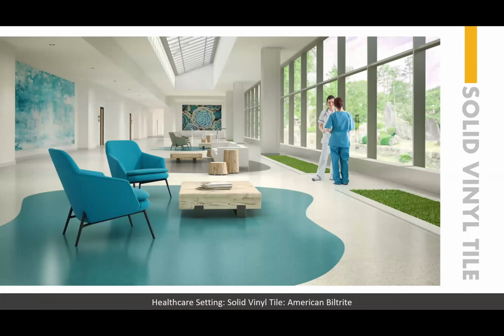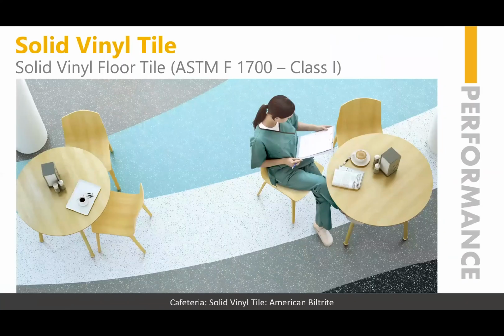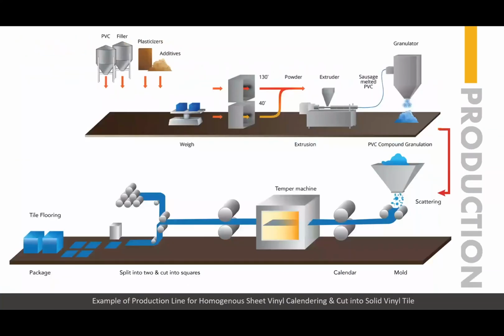Solid vinyl tile is another category, although others fall within some of the same ASTM methods, just in a different method or class. So solid vinyl performance is ASTM F1700 in class 1. There's two ways that you can make solid vinyl tile. One is the homogeneous sheet calendaring that we showed you earlier for the sheet product, and that sheet product is then cut into squares and into tiles. So that's one way of doing production for solid vinyl tile.